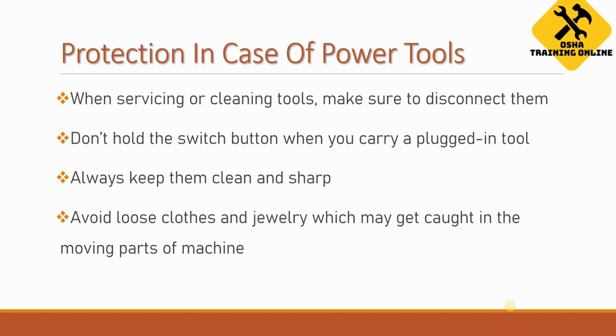Now lastly, we will discuss some of the protections in case of power tools. The first one is, when servicing or cleaning tools, make sure to disconnect them. If you are using electrical equipment and you want to service it or clean it, make sure that you have switched off the supply of electrical current. If you haven't, and you are cleaning it with water or something else, it may electrify you and it may kill or injure you. So make sure that it is disconnected.